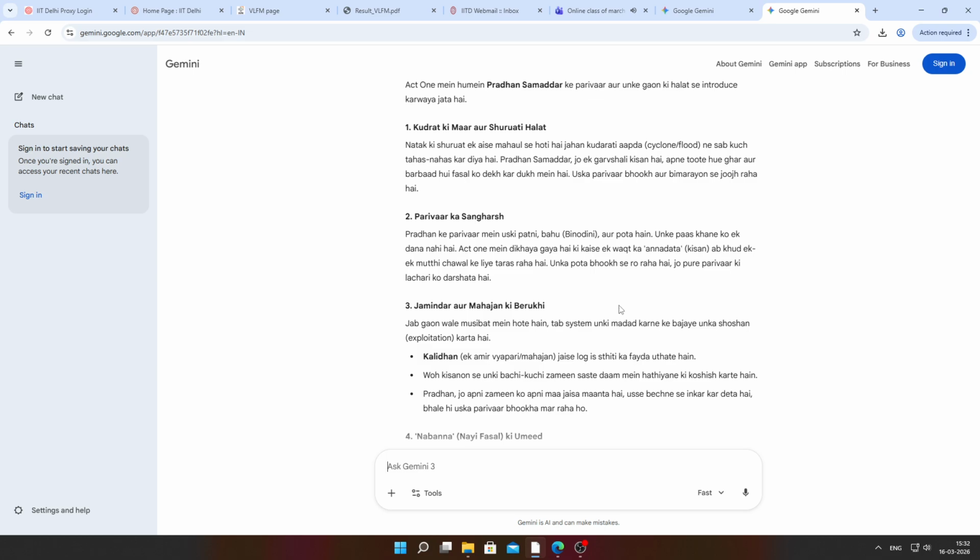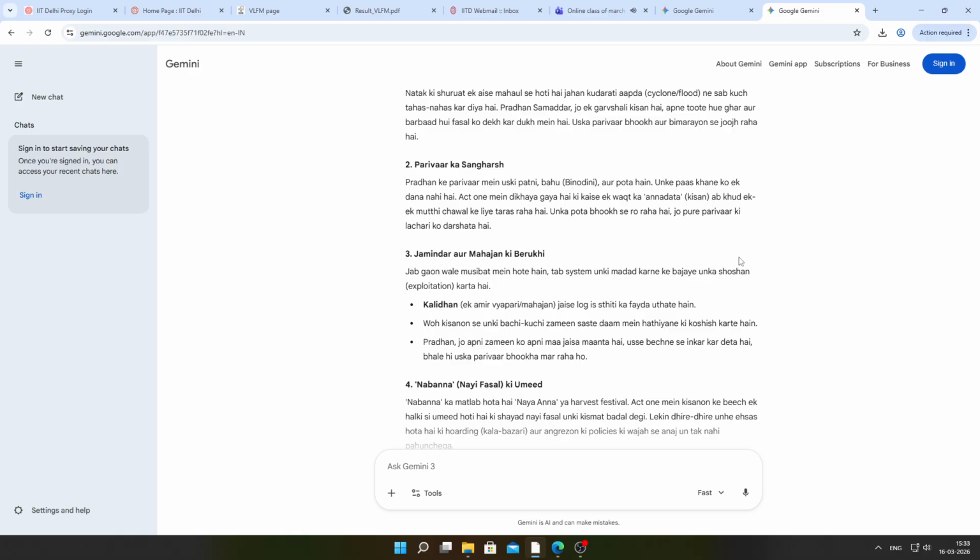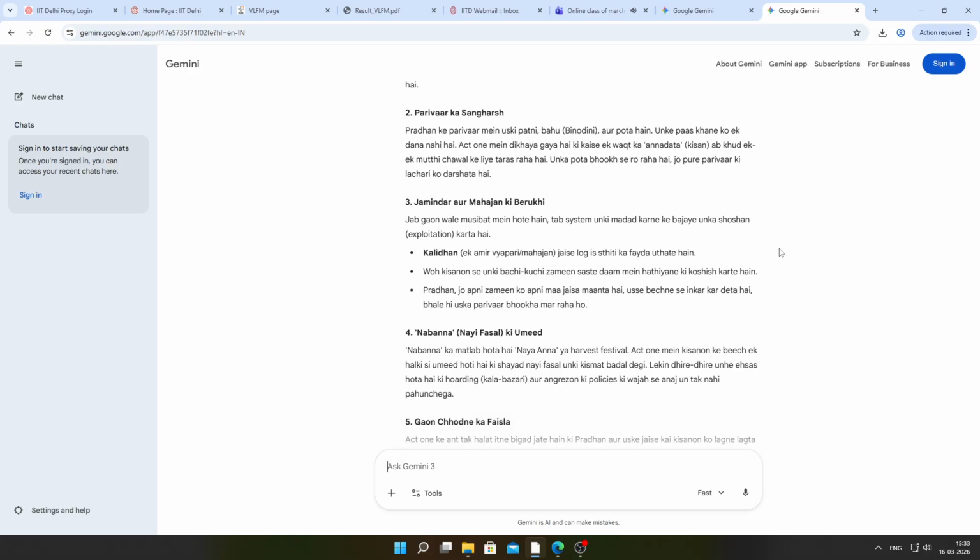And then we defined SOC, which was Q residual divided by the charge capacity of the cell, or total capacity of the cell. And then we defined DOD, which is complementary to SOC. It is 100 minus SOC or 1 minus SOC, depending upon whether SOC is expressed as percentage or as fraction.